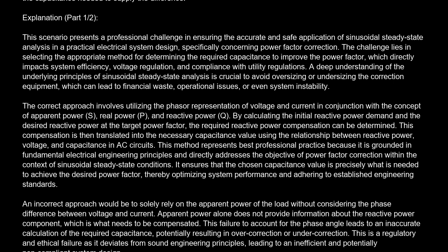An incorrect approach would be to solely rely on the apparent power of the load without considering the phase difference between voltage and current. Apparent power alone does not provide information about the reactive power component, which is what needs to be compensated. This failure to account for the phase angle leads to an inaccurate calculation of the required capacitance, potentially resulting in overcorrection or undercorrection. This is a regulatory and ethical failure as it deviates from sound engineering principles, leading to an inefficient and potentially